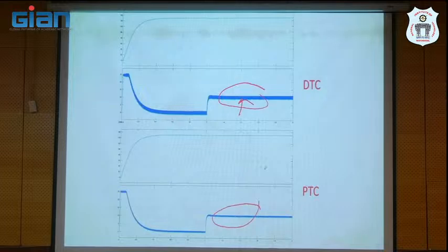Compared to the MPC method, the DTC method's dynamic response is very good, but the deviation between DTC and MPC is not that much, right? So by adopting the MPC, we can improve the steady state. Many scholars are focusing on improving the steady state performance. All of these are vector control only: DTC, MPC, field orientation. So you need not bother about the dynamic response. Your primary objective is to take care of the steady state response, right?